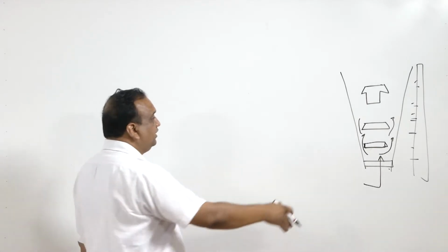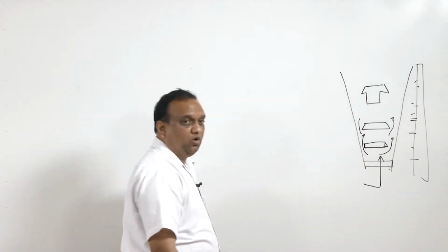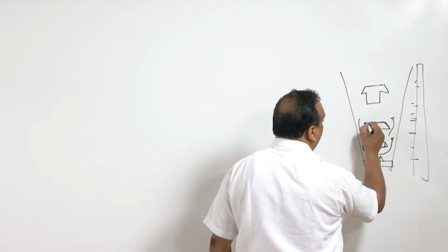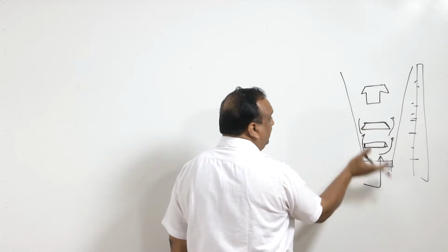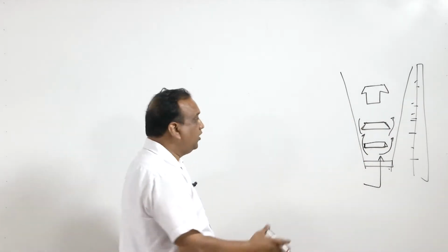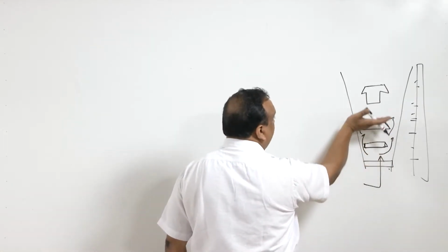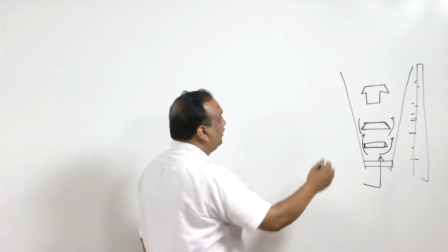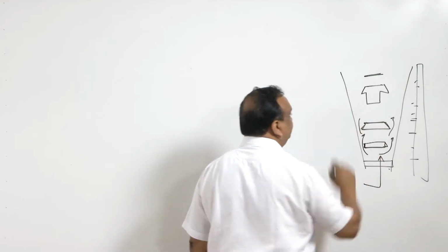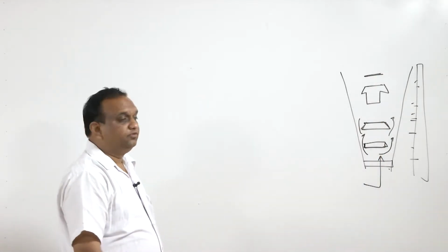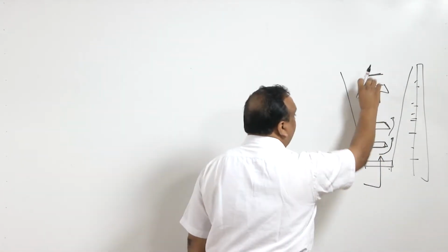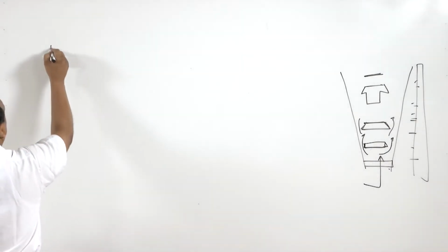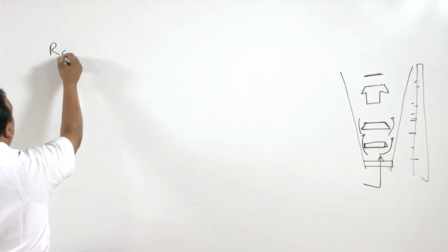But the issue is, what is the physics behind this? How does it come into the equilibrium? And how is the equilibrium decided? As we keep on increasing the flow rate, the bob keeps on shifting the position in vertical direction. For the highest flow rate, it will be somewhere here. Right. So, how the position of the bob is decided, and what are the forces which act on this rotameter, that we will discuss here.